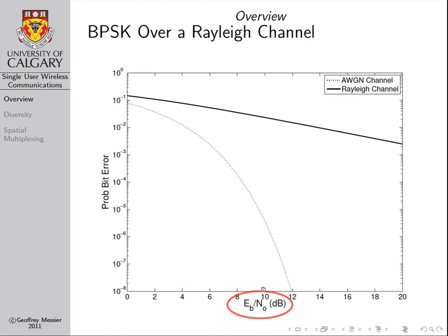And then, let's say you have a certain transmit power, 1 milliwatt, you have a certain large-scale channel attenuation, you have a certain level of thermal noise, and when you do that calculation, you determine that just due to large-scale channel effects, you get an average received signal-to-noise ratio of perhaps 8 dB.